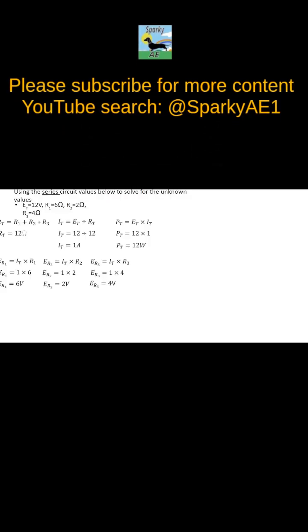Next, we find our current values at each resistor. For resistors 1, 2, and 3, we set the equations up, again using Ohm's law, as voltage drop at resistor 1 divided by resistor 1 value, and the same for resistor 2 and resistor 3. First resistor, we just divide 6 volts by 6 ohms.